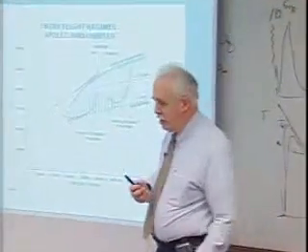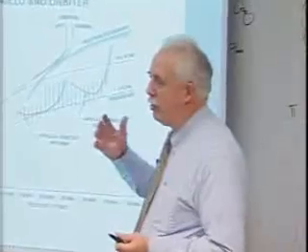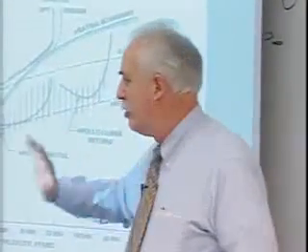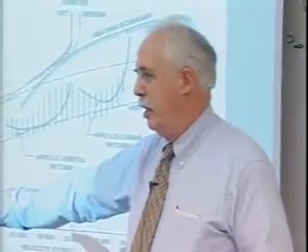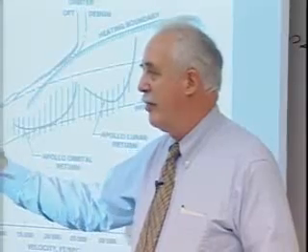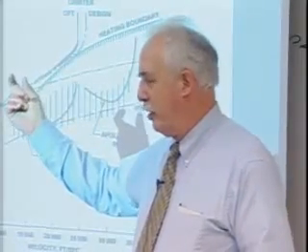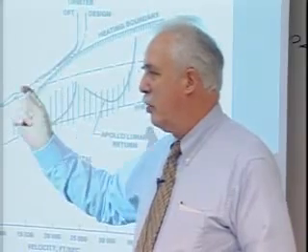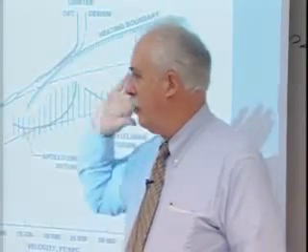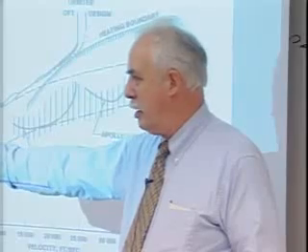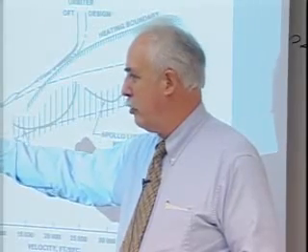Actually, from an ablator standpoint, one of the most efficient ways to come in is hot and heavy. Okay, go to a max heating rate, but keep that time down. You remember I mentioned the square root of time on the diffusion of the energy in. You want to keep that time down, and you're better off taking your lumps on heating rate. Heat load is really what designs.